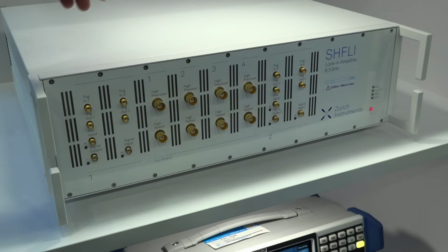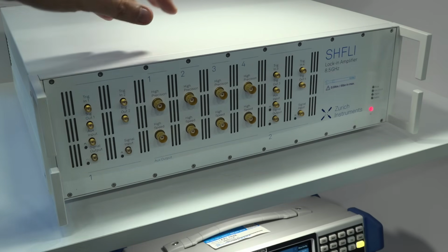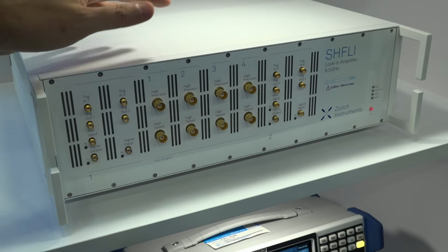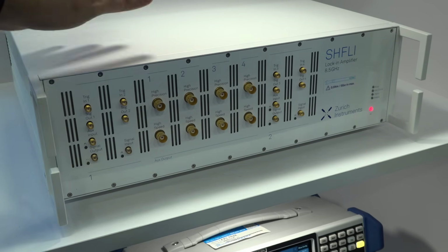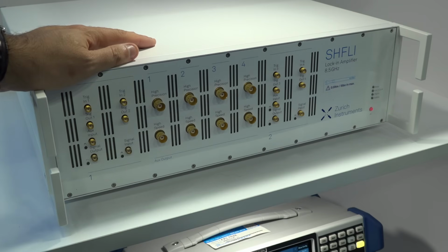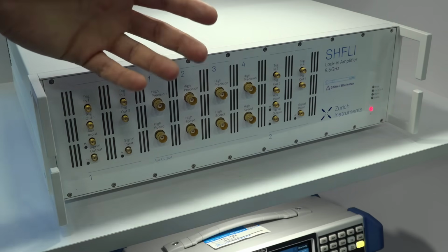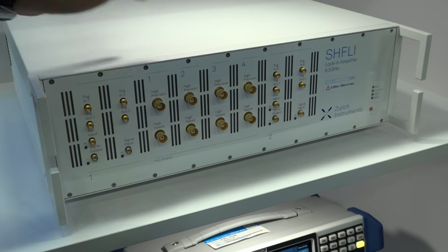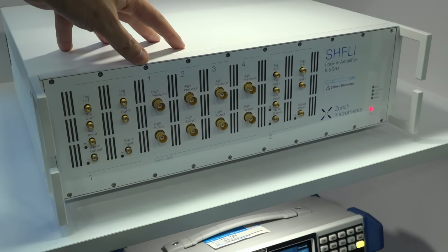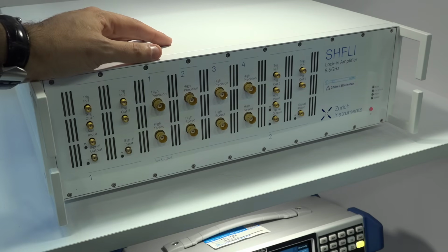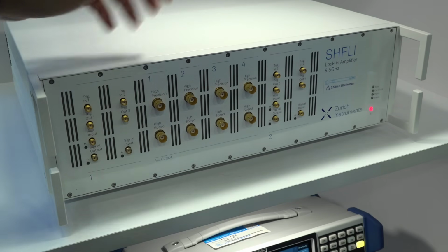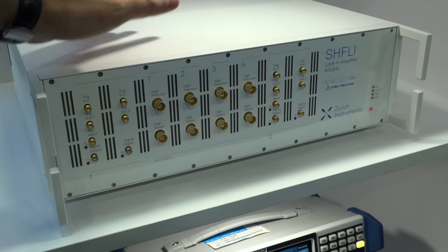And here I have the lock-in amplifier from Zurich Instruments, the particular SHFLI model. And if you've watched the channel, I have done a full extensive review of the Zurich Instruments lock-in amplifier in the past, built on the LabOne platform, which is a fantastic software platform controlling all of their instrumentation. Now, this lock-in amplifier goes up to 8.5 gigahertz. It has 8 modulators and 8 demodulators, being able to generate all these tones up to 8.5 gig, with instrument feedback directly on the front, with all the software features, PID controllers, and everything built in.